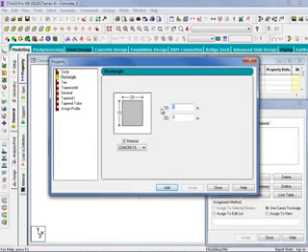I'm now going to enter my YD and my ZD of 24 inches each, and I'm going to make sure that this checkbox is selected. This will set the material to concrete, and here you can see all the materials I have currently available to me. So I'm going to select the concrete material, and then I'm going to go ahead and click Add, and I can see that a new item has started appearing over here. Now I can enter as many properties as I need for my particular model. I'm going to specify two different ones, one for my beams, one for my columns.